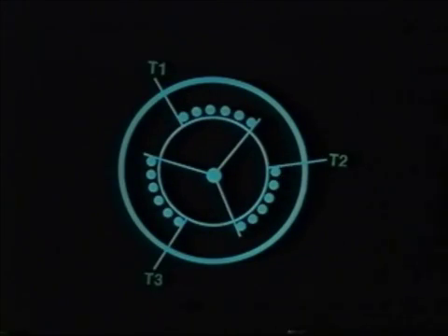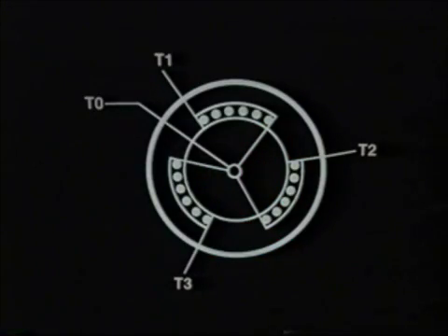These tied finished leads form a neutral point, and the start leads become the three output load leads. A fourth or neutral load lead may be brought out from the neutral point and is usually designated T0. The neutral load lead may be either grounded or left above ground. If the neutral load lead is left above ground, the unit is said to have a floating neutral.